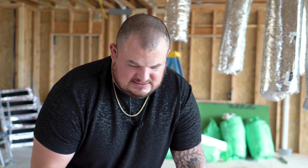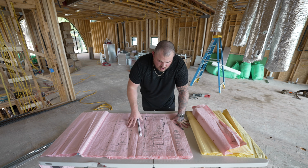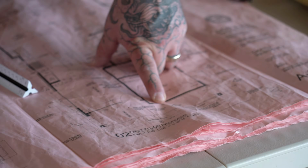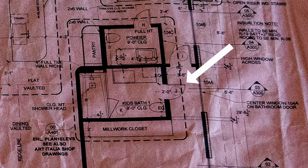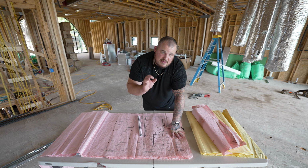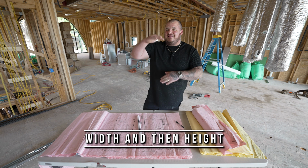Okay. Another thing that is very important, especially when you're bidding, is window and door sizes. You always want to push your architect to give you a window and door schedule and spell that all out. But oftentimes, what you're going to see is either a number. So I know that this window is window 102 on the window schedule. The same thing with this door. This is door J on the window schedule. But sometimes they'll list out some numbers on here. There's a few different ways they can do that. Just remember, every door and every window in construction, we talk about width and then height.